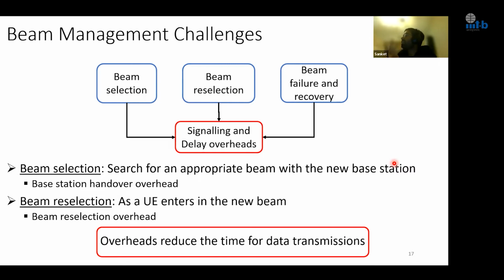And it seems that the beams will mostly be used at millimeter wave because we want to minimize interference, since the radio attenuation is already very high at millimeter wave. So beamforming helps in that case. Even if it helps in the sub-6 case, I think the main motivation for sub-6 in 5G is to have coverage, meaning that for the users who lie at the end of the cell, we would like to serve those users. So we can still use beamforming in sub-6; there is nothing stopping us from using beam management in sub-6. So it can be done for both. Thank you.